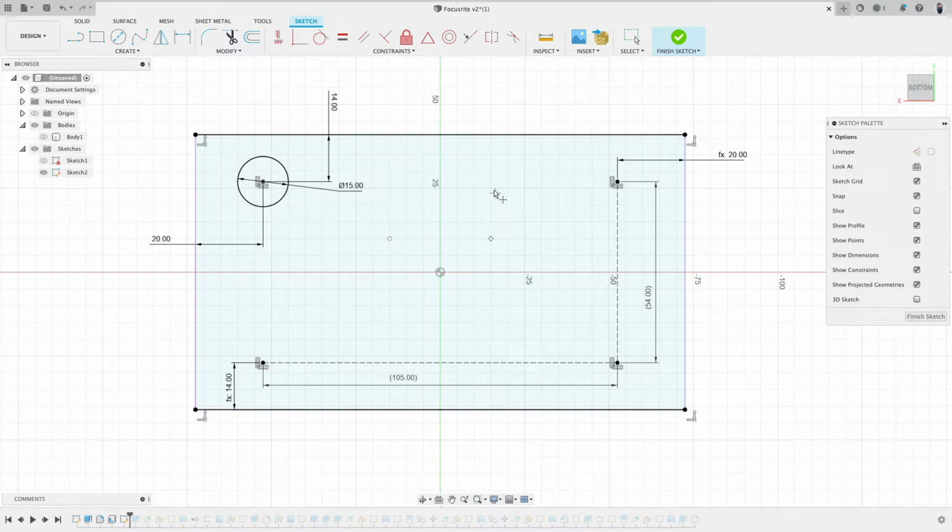And then to figure out the dimensions, see here I drew myself some lines. These lines I turned into a construction line, very good. And then via horizontal and vertical constraints, I aligned everything a little bit. Super easy. Some more dimensions.